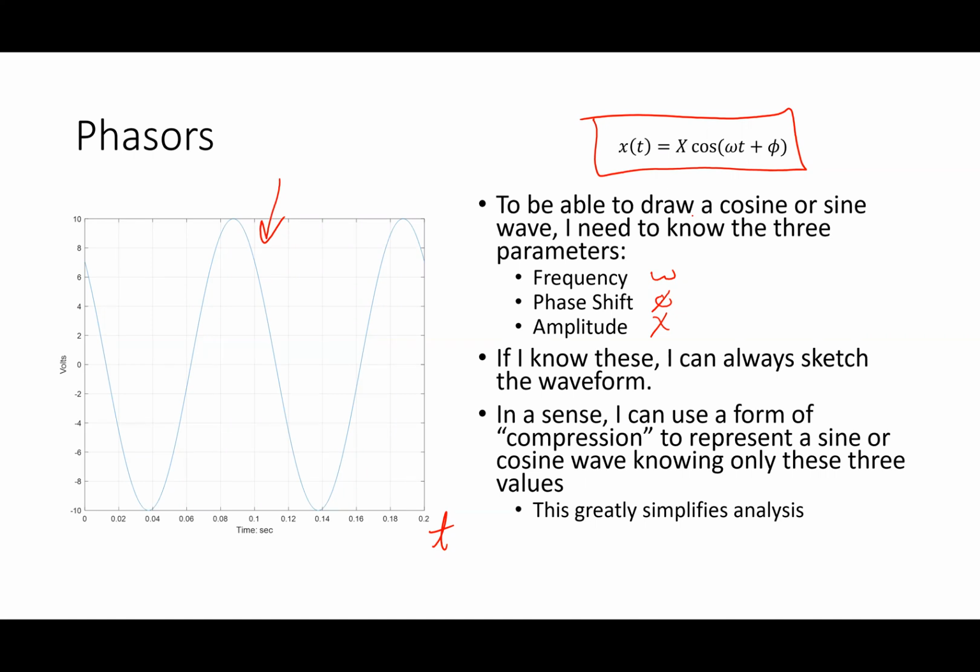I can basically say, you know what, I don't need to know what's happening at every given time, because the only things that happen as I go through a circuit are that I change the phase and I change the amplitude. And so we can actually just track what happens to those two things and forget the time stuff, right? That makes things a lot simpler. That means if I don't need to track the time, ultimately it means I don't need to do differential equations, all right? And it gets differential equations out of the picture, all right? That's what's really important for us, okay?